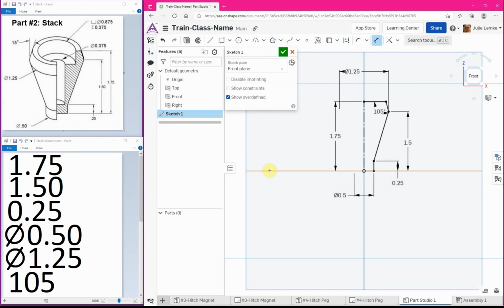There we go. Alright, so before I can close out our sketch, we need to, again, remember, undo our construction line, and now we got that gray area again. So now we can see that all our lines went from blue to black. We have that shaded area, so we are all set to revolve. So this is what I said by we're just drawing a piece of it without the hole. We're just drawing that shaded area without the hole.